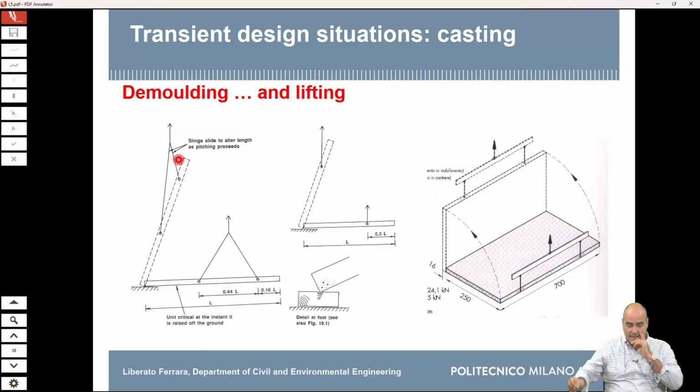If you can balance it, it's better. But the reaction force at the pinning point equates to the largest part of the weight of the element on a single point. The corner is a single point. So you will have a concentrated force, which risks locally breaking the concrete.